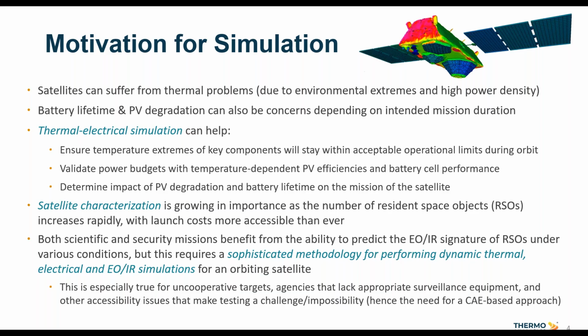And thermal electrical simulation can help with these two concerns by helping ensure that the temperature extremes of the critical components of the satellite stay within acceptable operating ranges during the orbit. Also validating the power budget by incorporating the temperature dependent performance of the battery and efficiency of the solar panels, and making sure that works with the electrical components that are on board and need to be powered to fulfill the mission of the satellite. Then going beyond that, this sort of simulation can help determine the impact of battery lifetime and solar panel degradation on the mission lifetime of the satellite.